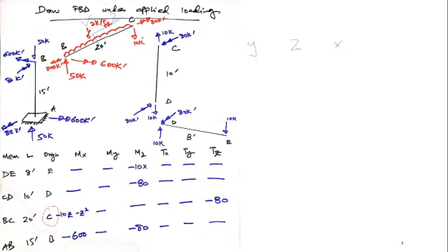Okay, this 10 kip is forming a moment, 10Z. It's forming a clockwise moment, so the resistive would be minus 10Z. So I have applied a minus 10Z. From upwards I have a load that is 2 kip per foot, and 2 into Z, because it is acting up to section Z, up to this length 2Z, and the moment would be Z by 2, Z squared. It is forming a clockwise moment because it is acting downwards, so this would be resistive as well. That's why it's a minus here.